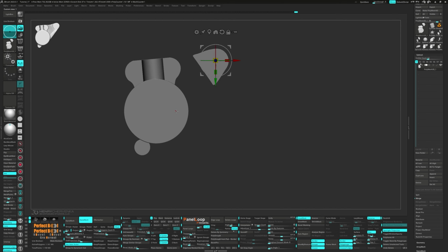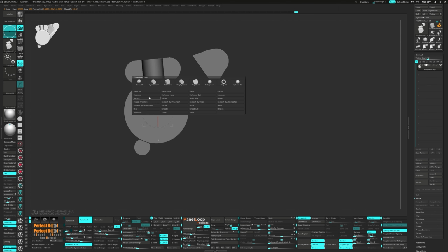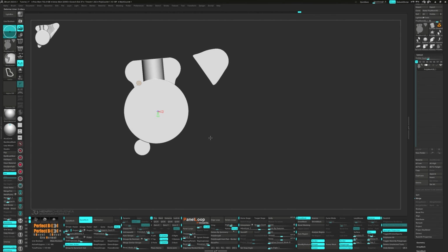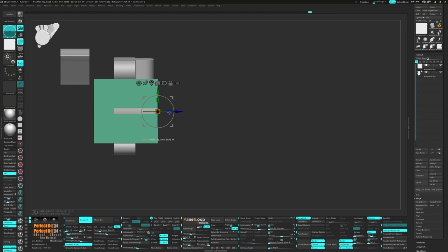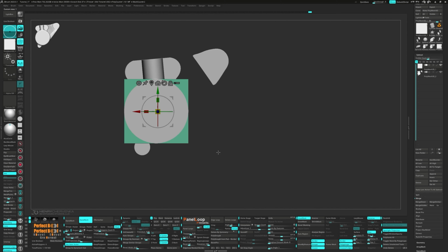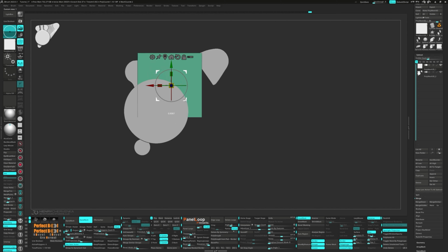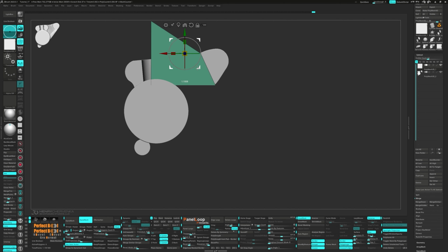Go ahead and mask the model. Fire up the gizmo and from the gear, select Polycube. Invert the mask and split unmasked points. Now press Unify and delete loops. Let's scale it along the Z-axis. Then mask it and maneuver it into place with the gizmo.